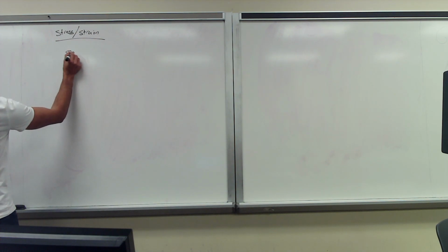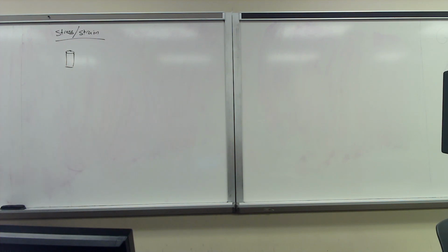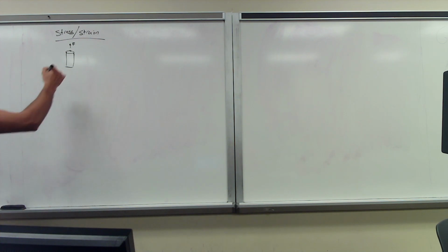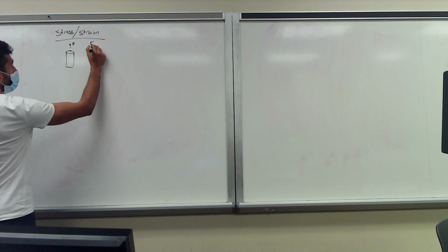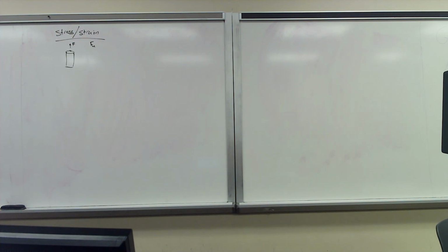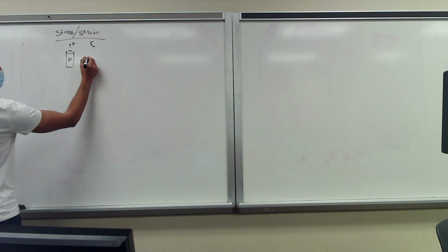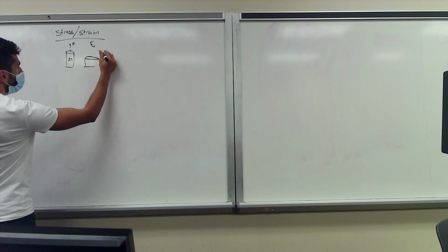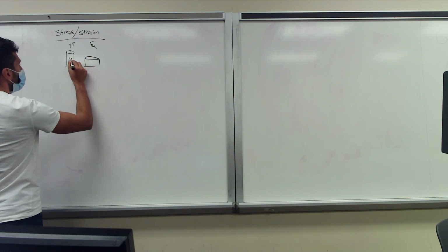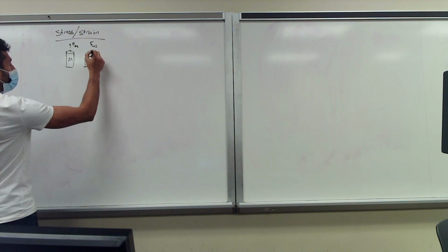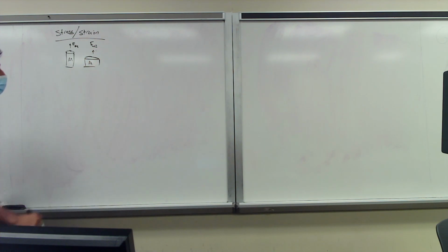So regarding stress and strains, the idea comes from the fact that if you have any specimen and you want to know something about when it fails. In early days they figured out that if I apply a force to it, at a certain point it fails. So I get an ultimate, that's my failure load. And if I have material 1 and I change the geometry of it, then suddenly FE1 and FE2, even though they're the same material, are not equal.